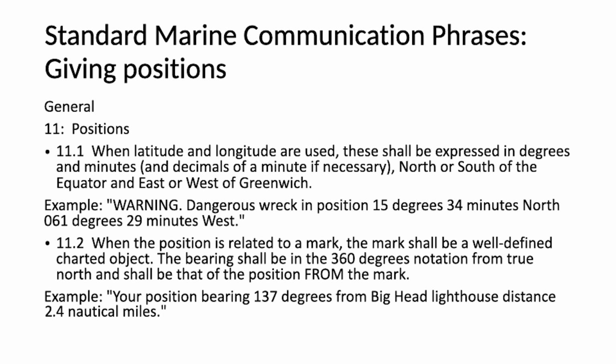When the position is related to a mark, the mark shall be a well-defined charted object. The bearing shall be in the 360 degrees notation from true north and shall be that of the position from the mark. Example, your position bearing 137 degrees from Big Head Lighthouse, distance 2.4 nautical miles.